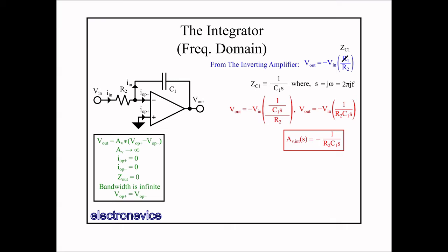These offsets are impossible to eliminate completely and are very important non-idealities that I will explore in detail in later videos. Additionally, the integral doesn't specify a starting time point, which means it's always integrating when the op-amp is powered, and powering up an op-amp produces some unclear initial conditions that could vary greatly from op-amp to op-amp and power-up scheme to power-up scheme. So complications in real op-amps are significant enough that we should address them to some degree even now in this ideal op-amp world. There are a few ways to mitigate these effects, which we will explore now.